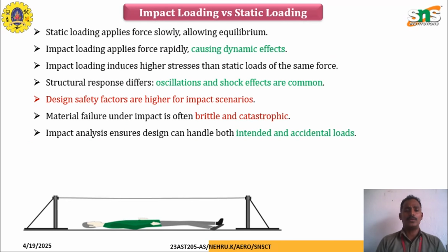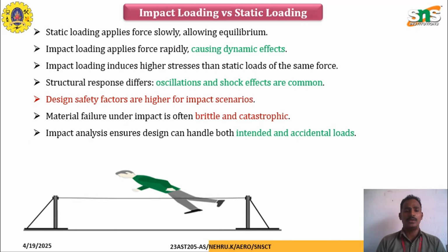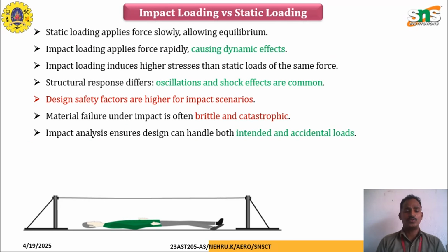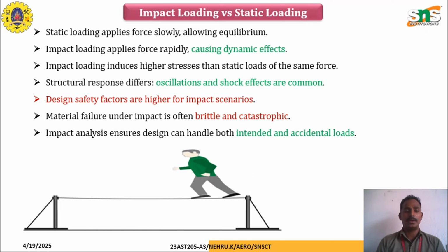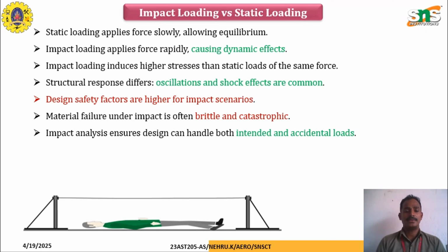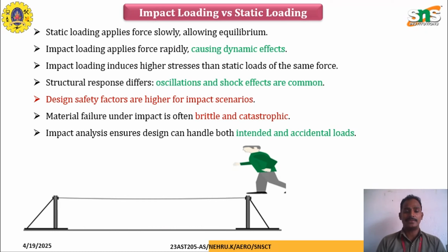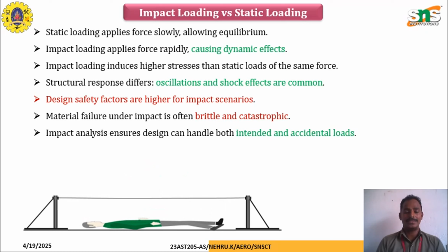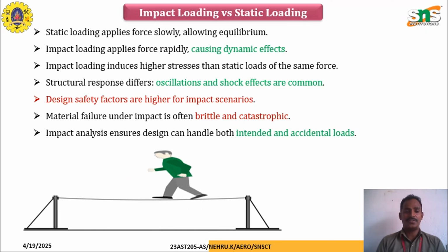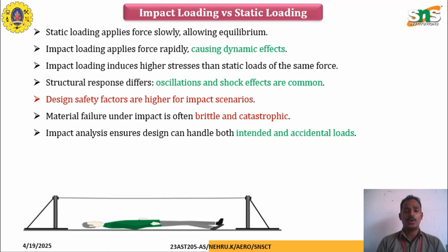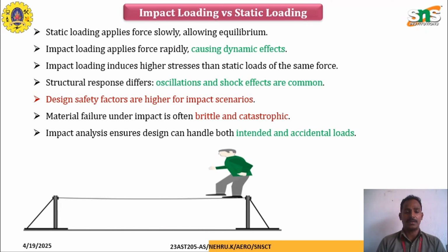Next, impact loading compared with static loading. Static loading applies force slowly, allowing the body to remain in equilibrium, whereas in impact loading the force is applied rapidly, causing a dynamic effect. Impact load produces higher stresses than the static load for the same force. The structural response differs, and oscillations and shock effects are common in impact load.